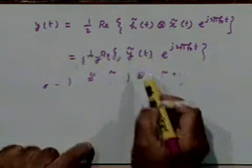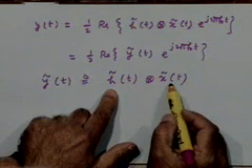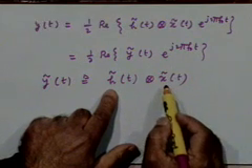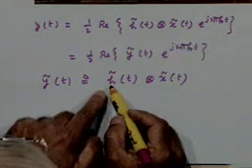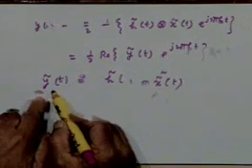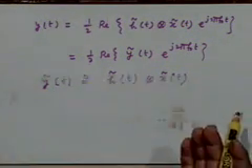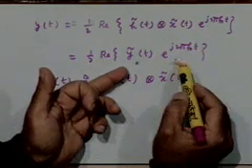I could as well do the convolution directly of the low pass representation of the bandpass signal, the complex representation, with the complex low pass representation of the bandpass system, the bandpass impulse response. Find out what the output would be, which will obviously be a complex low pass signal. Then go and do this operation.